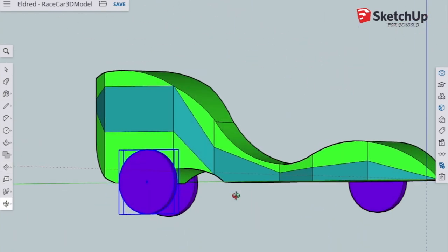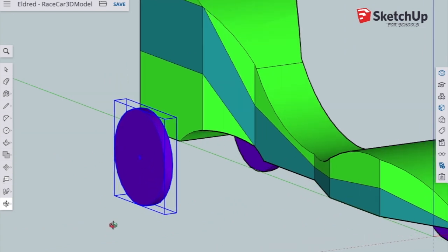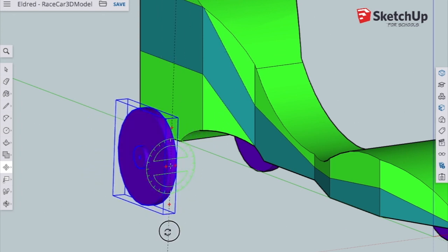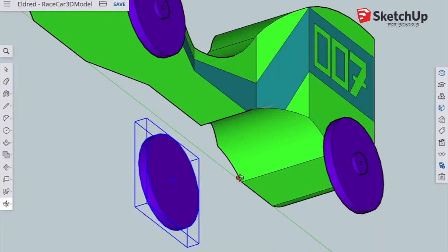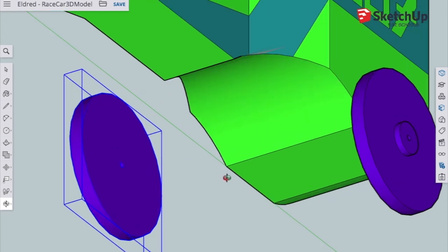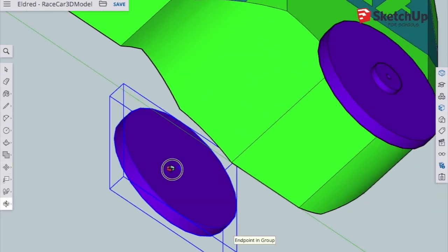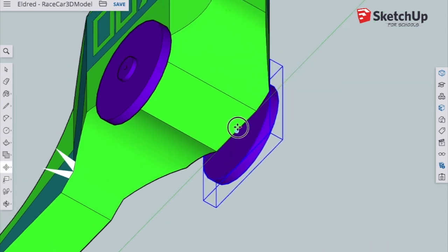Problem is it's inside out. I want to flip it around the other way. So I need to go to the move tool, turn it around 180 degrees, and then go back. What I'm doing is grabbing a hold of it at this hub, and letting it snap to the midpoint along this line. So it's hitting one line, hit the other one. Okay, so if you have some trouble getting it to go to a spot, try changing your view and do it again. There it goes. It wants to hit that line now.